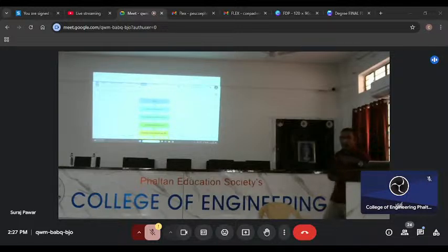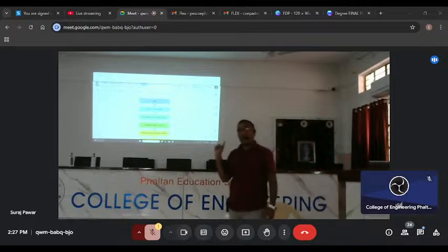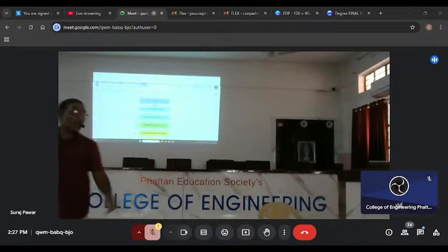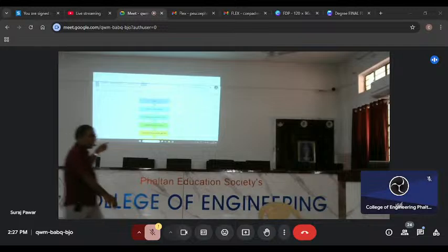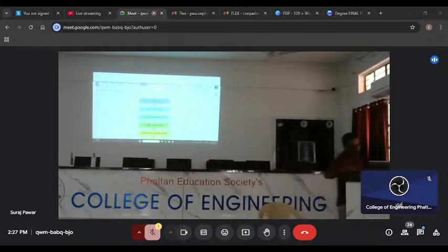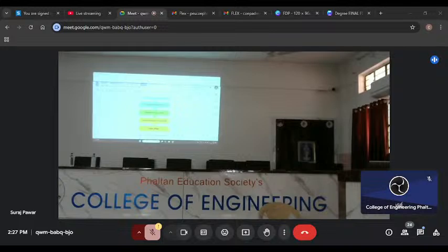This is a new area. Start with payload requirement, set target for buoyancy force, identify aerostat shape, estimation of gross lift and PSL, then final design. So even though it is a new area, I am able to work because I got an idea how to formulate the problem. Okay.